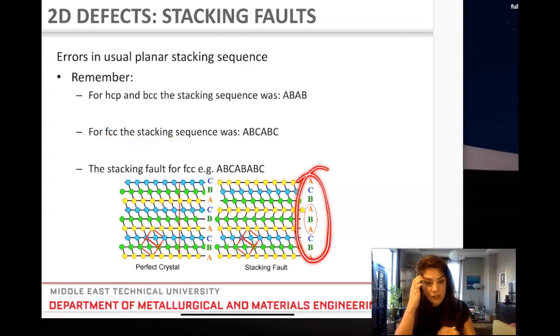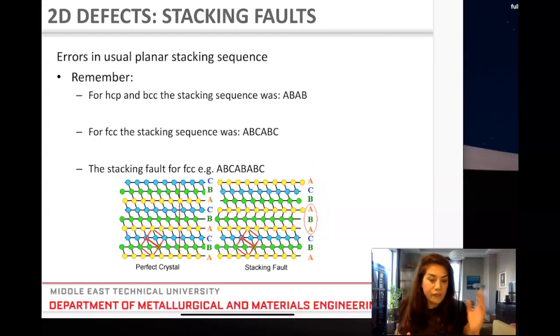And this example here just shows very well. If there is some imperfection in that stacking order, like, for example, instead of having ABC, ABC, ABC, I have, again, I'm making a picture hunt, right? What is different between these 2 guys? I have ABC, AB, oh my God, there's no C plane and there's an A plane getting in between, right? So that specific missing plane, or just instead of no C plane present here, is a stacking fault. Fault in a stacking, that's called a two-dimensional defect. It's an imperfection in two dimensions, right?